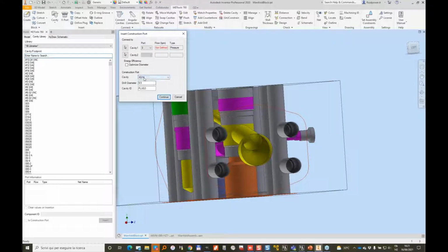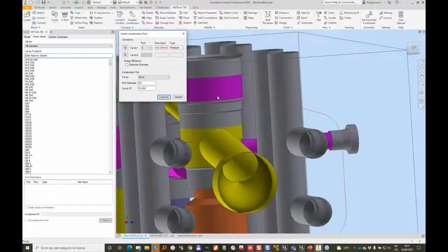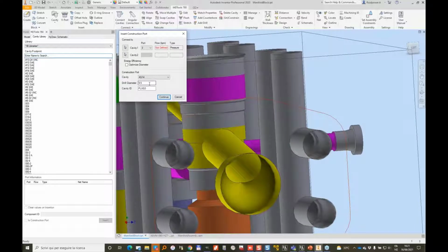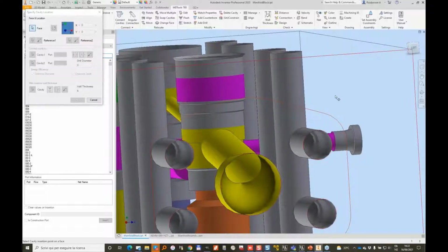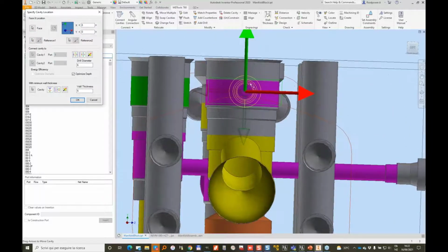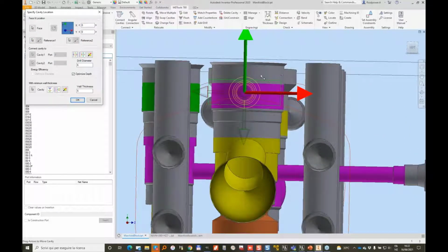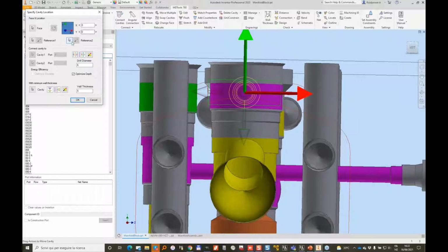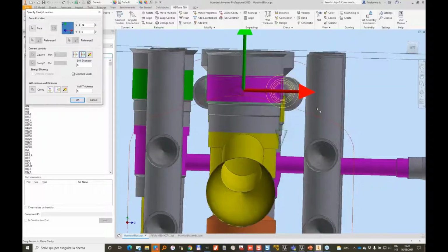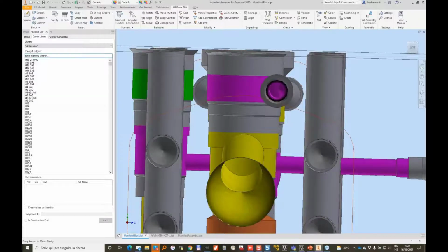By default, it will take the 1x4 because this cavity is demanding a 9.5 millimeter diameter. So it takes the closest plug that can do that drill, but we need just a pilot line. So 6 is enough. And we don't want to go on top of the yellow line. This will create problems with connection. So we stay tangent. A tangent will stay too close to the bolt hole. Let's move slightly to the left. This is enough. Later we'll do some wall thickness checking in our design.